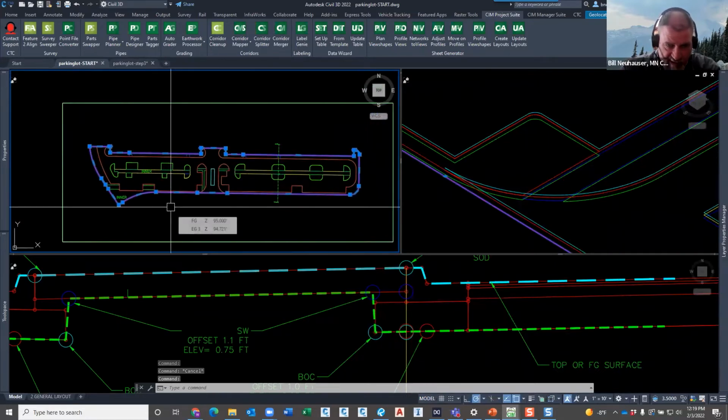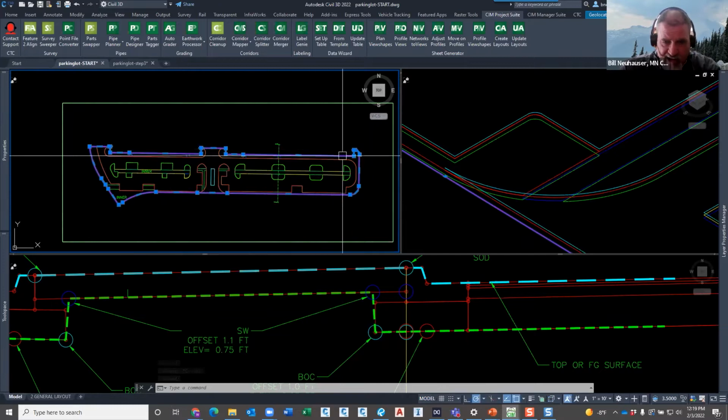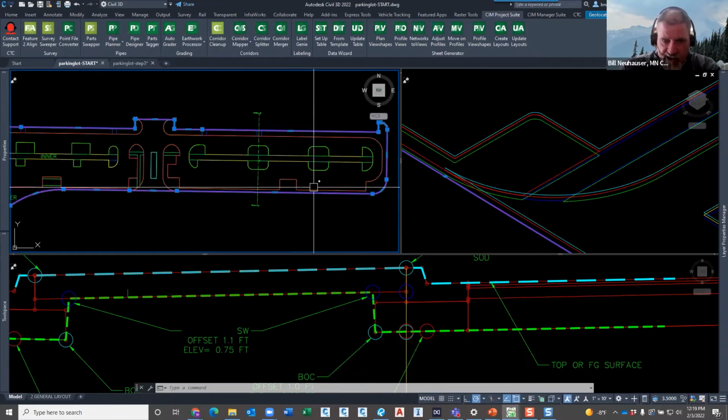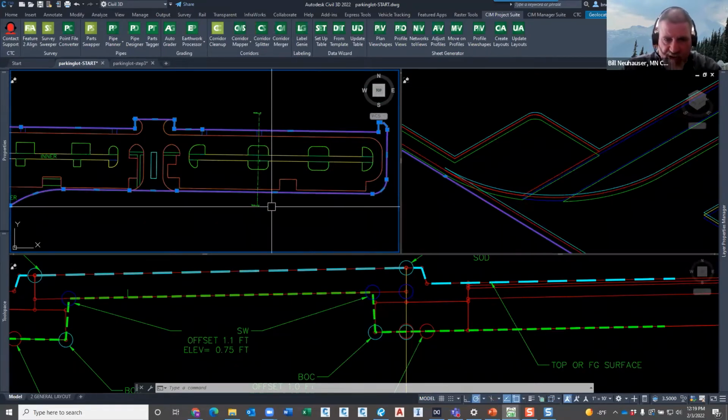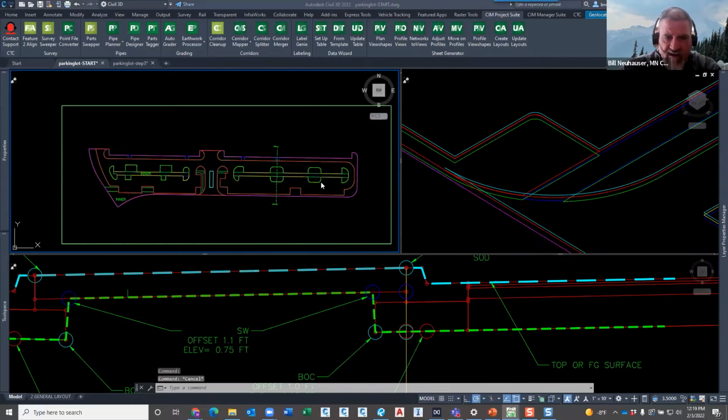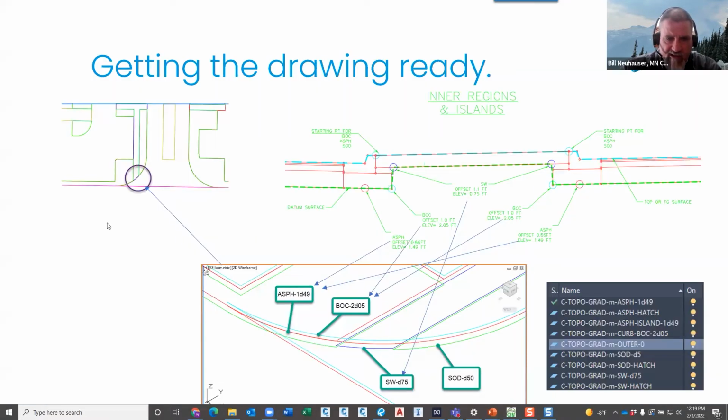Okay, that's something else I've got to create because I need it. This is set up to be in a zero offset, zero elevation. That way the whole surface kind of ties back into existing ground out there. Okay, if not, we end up with a gap on the edges. Okay, and let's go back here.